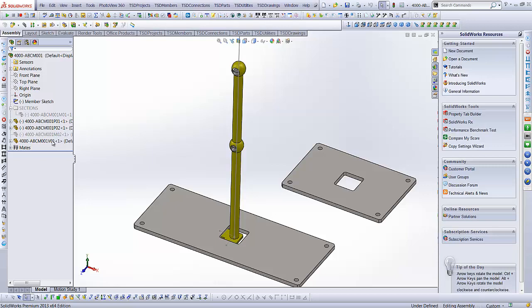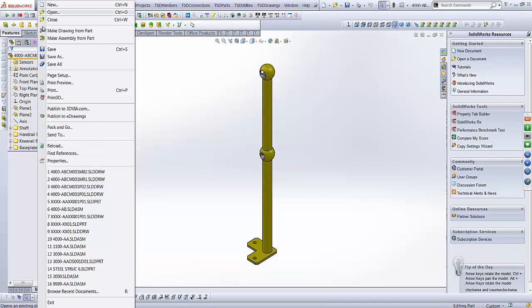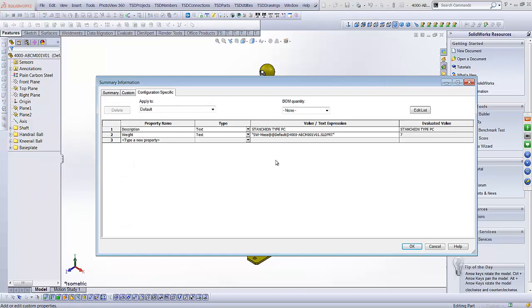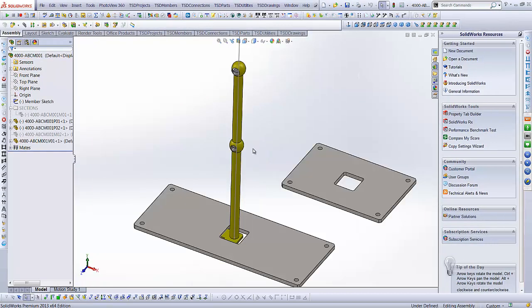The bill of materials, when created, uses these in different processes. With vendor items, if you open up the part and go into the custom properties, this information on a vendor is already predefined. So you want your weight and the name of your stanchion, in this instance, to be included. When you run your BOM compiler, it doesn't add anything to the custom properties for a vendor, whereas with a member it does, and a plate it does. So that's why we've named them the way they are.